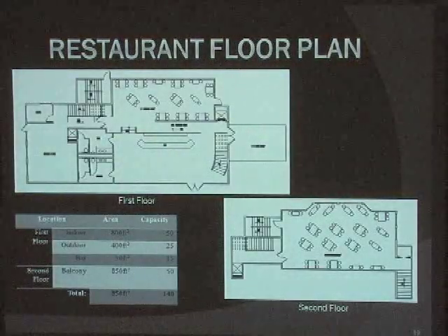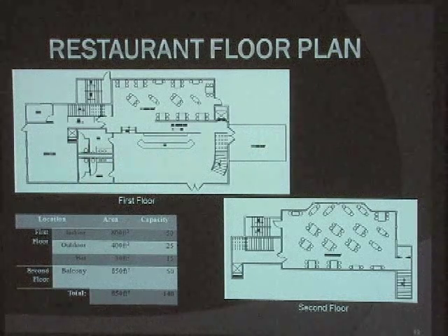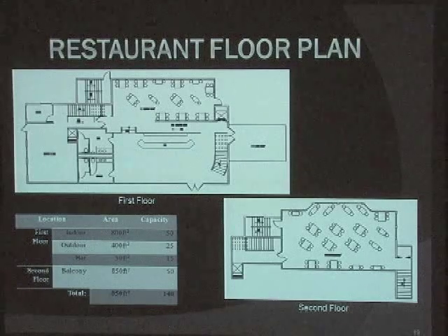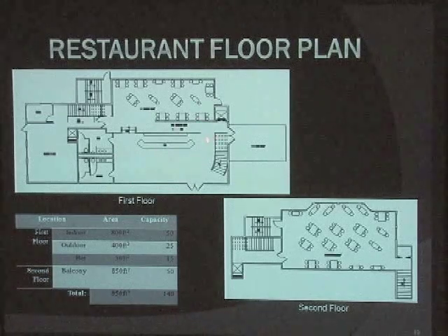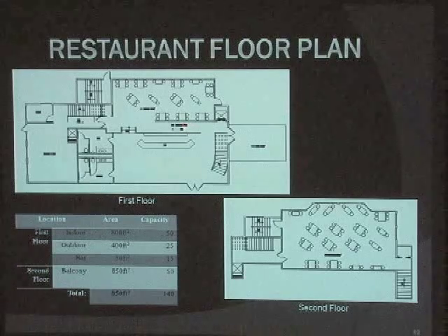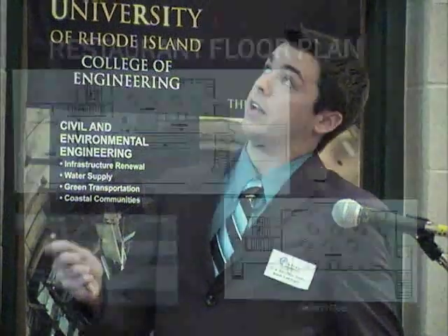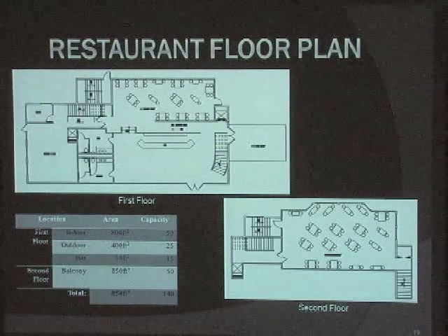The inside floor plan, we based this off of, if you're going to have an ocean view restaurant, you want to optimize ocean view for all the patrons. So we have a split level and you enter at the middle level, and then this is a 42-inch half wall here, and there's a handicap ramp, 18-inch drop to the bottom seating level, and then stair access to the top seating level. There's also access by elevator, and the entire structure is fully ADA compliant.